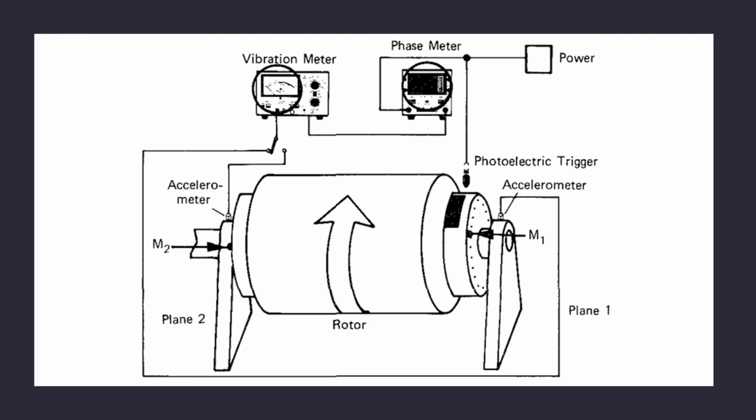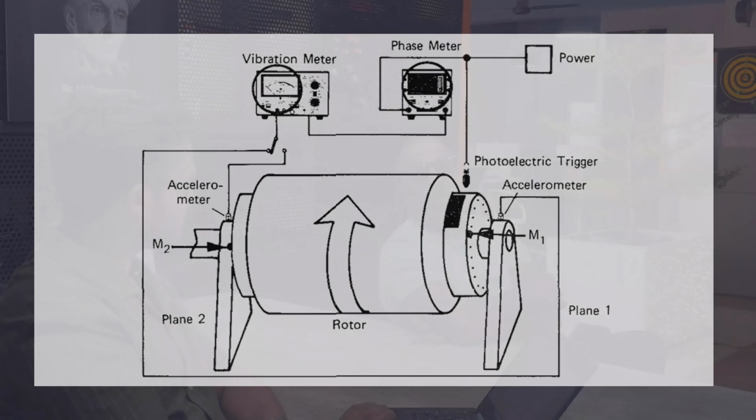I took up one of the cases that we handle here, which looks like a simple one: field balancing of a complex rotating equipment, more connected to process industry, and the intricacies around it, because the project is about a variable drive with a fluid coupling as an interface, which is a challenging task for both vibration analysis and balancing.